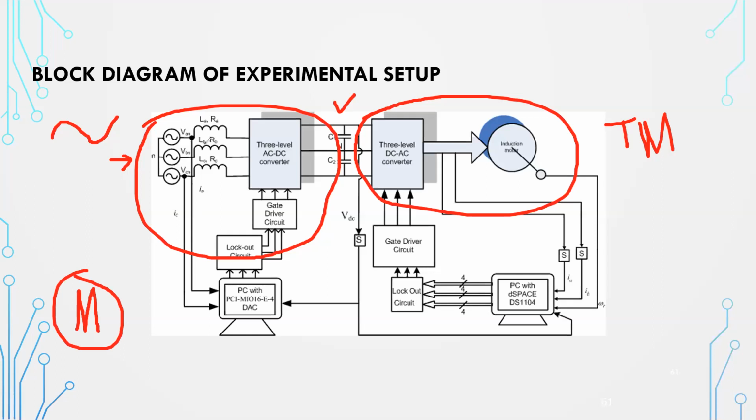It is generating a lot of harmonics. So nowadays the railway wants that we should not generate any harmonics because it is very high level. That will impact the grid structure. That is why we design a utility friendly converter.